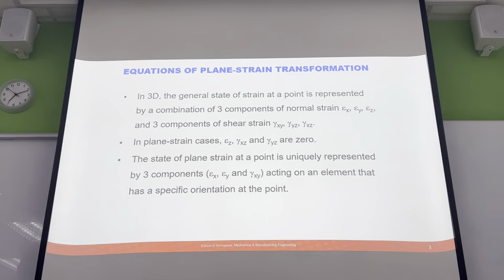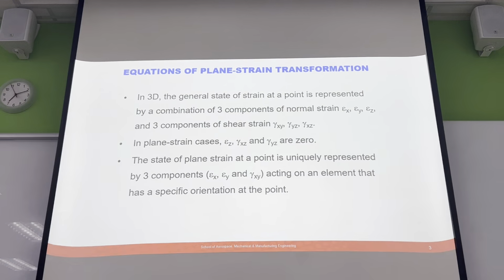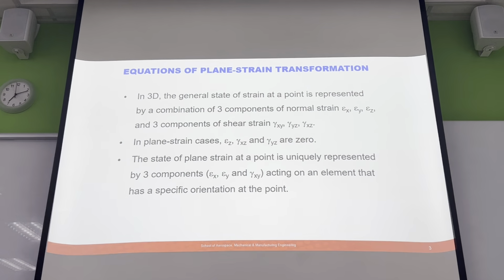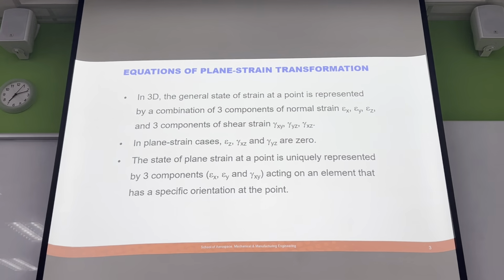with strain, if you want to know the full 3-dimensional strain status of an object, of an infinitesimal element, you need to know the strain in 6 dimensions, the same 6 dimensions. So how much is the x face moving in the x direction, how much is the y face moving in the y direction, the z face in the z direction. So that's